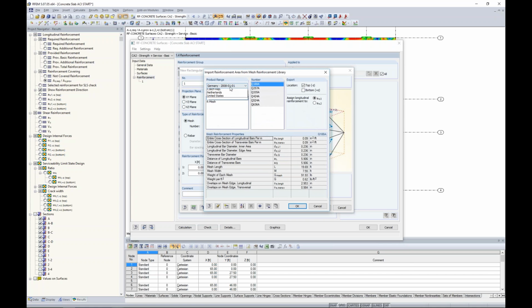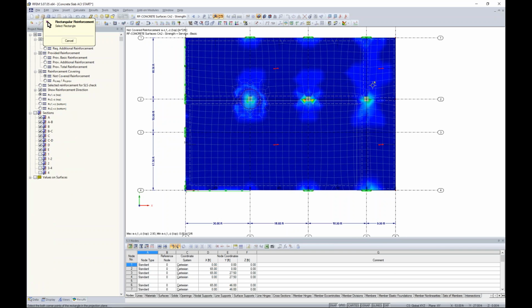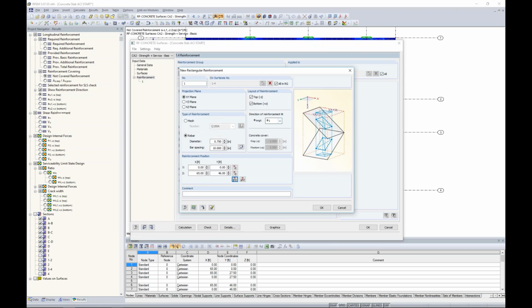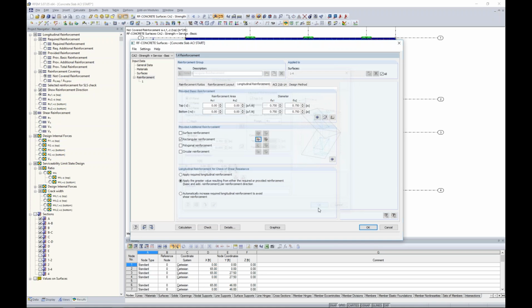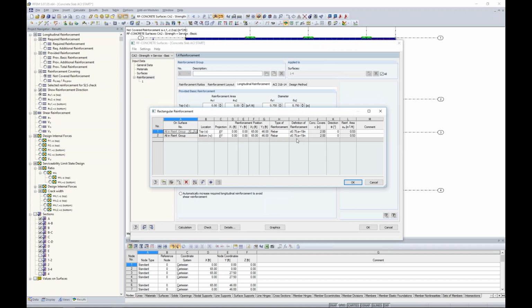Again, we can pull out this welded wire reinforcement if we'd like according to these rolls or sheets, or we can define our diameter of our rebar at 0.75 at 10 inches on center. Now, I want to apply this to both the top and bottom in the 0-degree direction. And I simply just choose my 2 points to apply my number 6s at 10, and I'm going to choose the entire slab here. I click OK, and now I have this table available that I can see I've applied to both top and bottom in the 0-degree direction, number 6s at 10 inches on center.